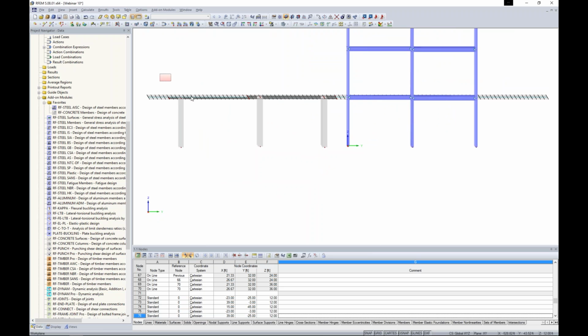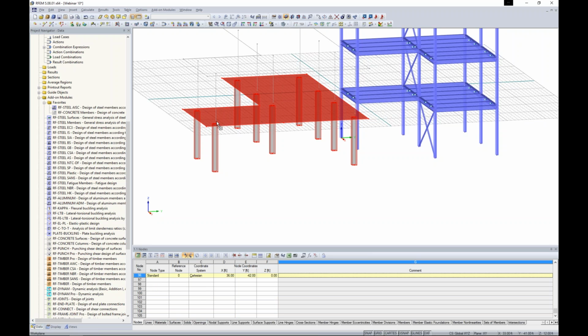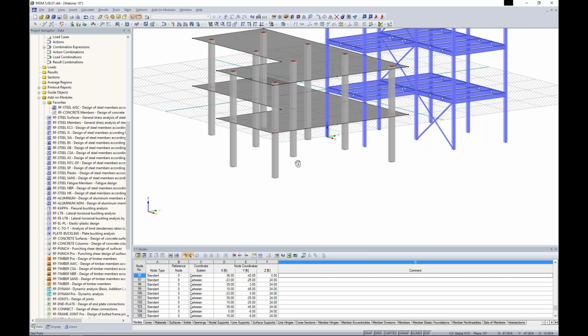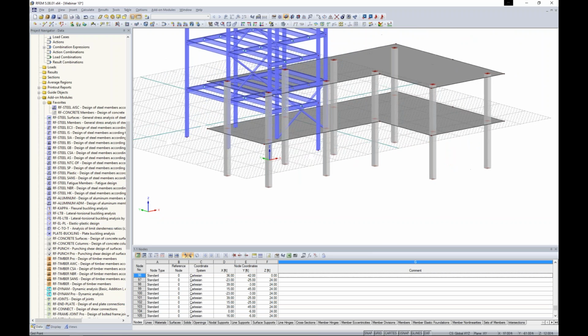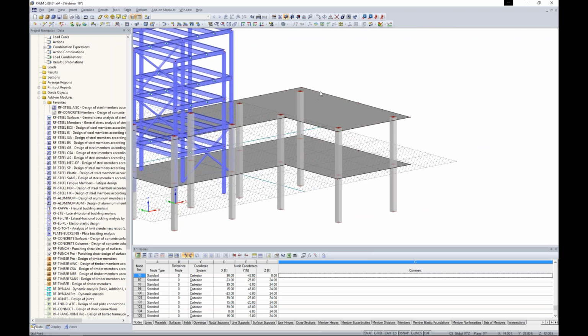Copy tool. So the next thing I'd like to do is maybe create a second floor. Well, I can hold down my control key, use my drag and drop feature once again, and now I have my second floor here. The reason that I skipped the column over on this side is because maybe I'd like to create a rib type beam underneath my slab here.